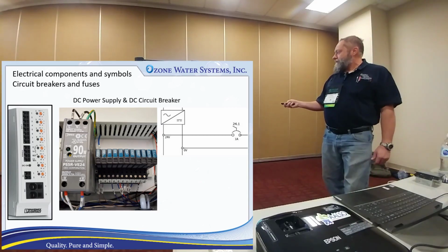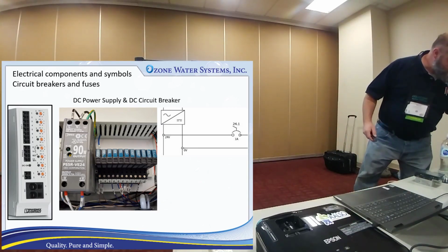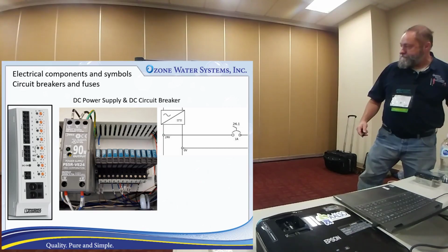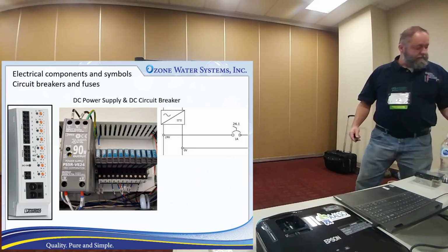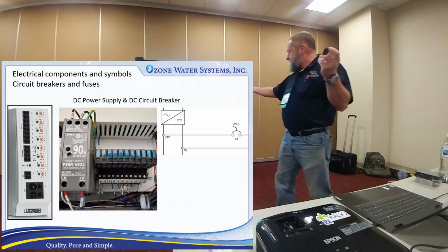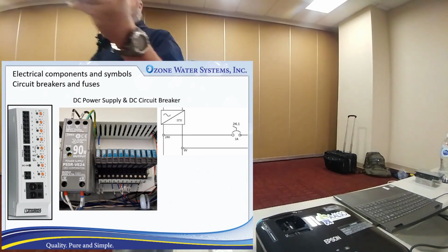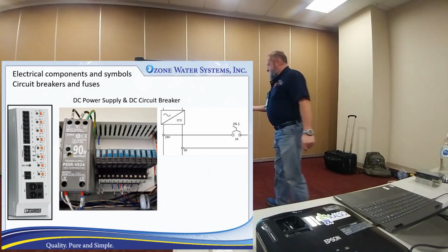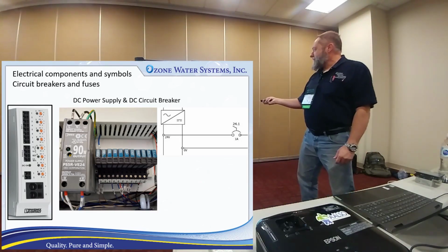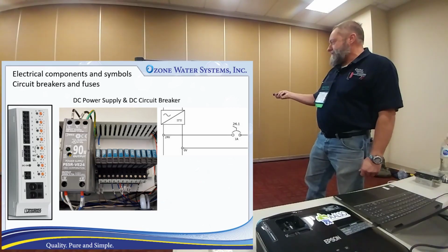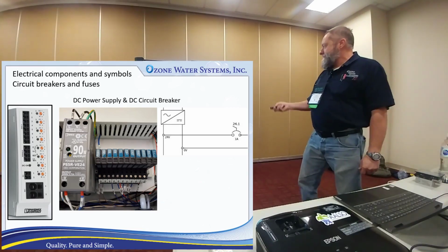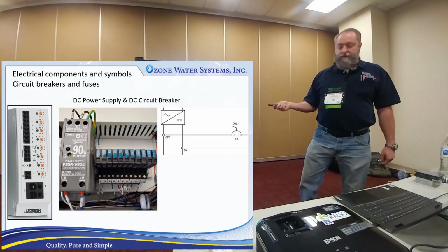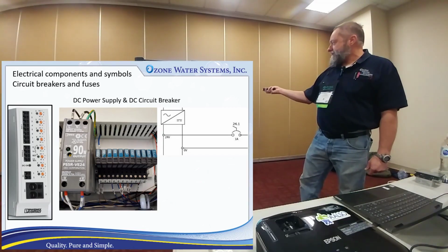Let's see, where's that? There it is. Here's an example of one of these little blue circuit breakers. If it goes off, it pops and goes up, and you can reset it. It's actually just almost like an automotive type ATC fuse where the plug will fit. Those come in all different ratings. They go on a base that allows you to just line them up however many branches you need. And they're quick and easy to identify if it's tripped or not.